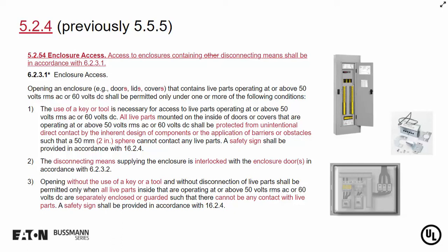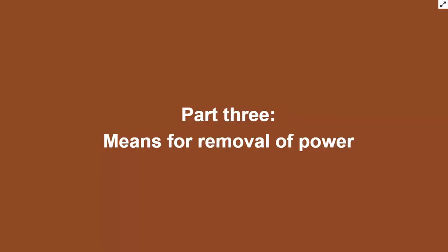So it's kind of difficult to see there. But what I intended to show you is that if I was to open that enclosure on the bottom, essentially there's a piece of plexiglass which would provide the required protection and not allow me to contact any of those live parts in there. So that's kind of how we would denote that.